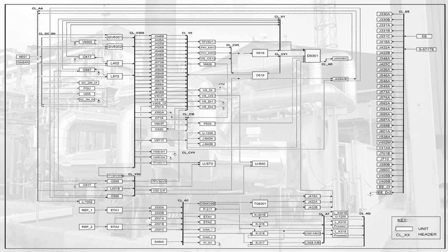The initials used to identify the entities of the system are: J pumps and ejectors, GV or L furnaces and boilers, M heat exchangers, O or P vessels, TF valves, and V blowers and compressors. The utilities that are considered in the optimization problem are superheated steam, V30S, saturated steam, V30, and its condensate, CV30, 5 bar steam, V5, and its condensate, CV5, and 1 bar steam, V1, and its condensate, CV1.